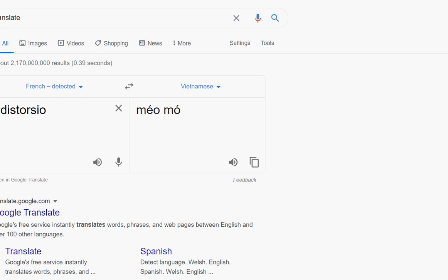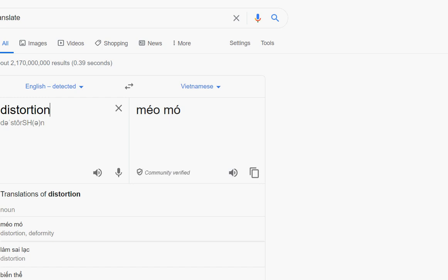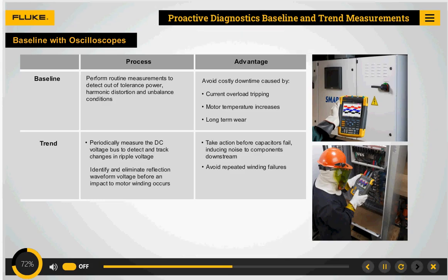Trending the DC bus voltage is useful to identify pending malfunctions. A DC voltage value that is too low can cause the drive to trip. As the cause, the mains input voltage is probably too low, or the input sine wave might be distorted by flat topping. If the ripple's peaks have a different repetitive level, one of the rectifier diodes is possibly malfunctioning.